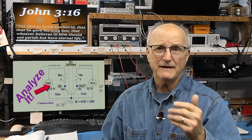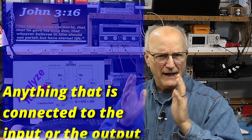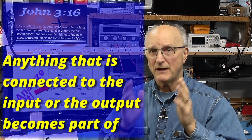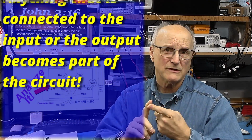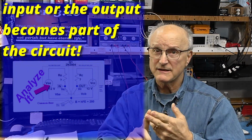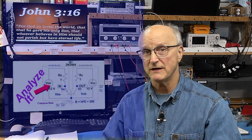I have a very important additional note that you must absolutely remember when creating a transistor circuit that doesn't live by itself. Anything that is connected to the input or the output of a circuit becomes part of the circuit. They become either current sources or current sinks that can and will change the operation of the circuit. So you've got to pay attention to this.